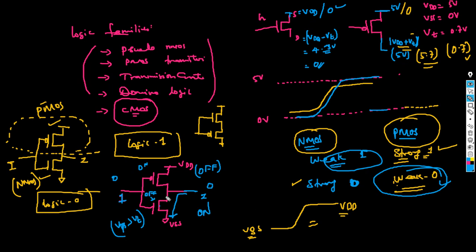Forget about depletion. There is no depletion. You are only in enhancement type, in which you have to apply a voltage to make the transistor work, or to turn on the transistor you have to apply a certain voltage at the gate. So there is no depletion. That is just in terms of concept I brought in and told you, but we don't use the depletion mode anywhere in our designs.